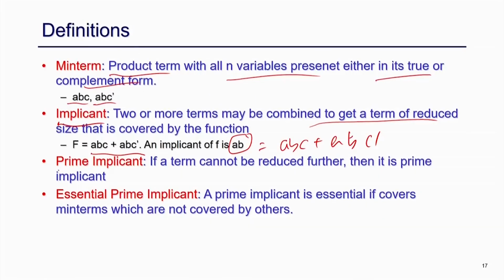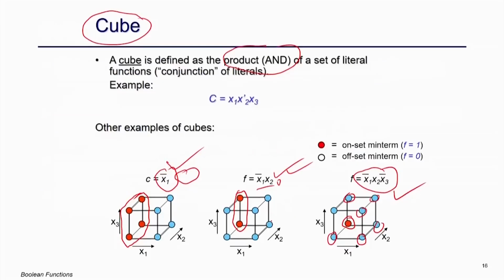And then what is important here is a prime implicant. So we try to grow. For example, if you have these 4 variables, initially you might have all 4 min terms individually. Then you try to grow it to an implicant which covers only these 2, then another implicant which covers these 2. Then you can expand further, you get this term x1 bar which covers all these 4. Then this is called a prime implicant, because now I am not able to grow further. Even if I grow, assuming there are only 4 onset here, I am going to cover some offset.